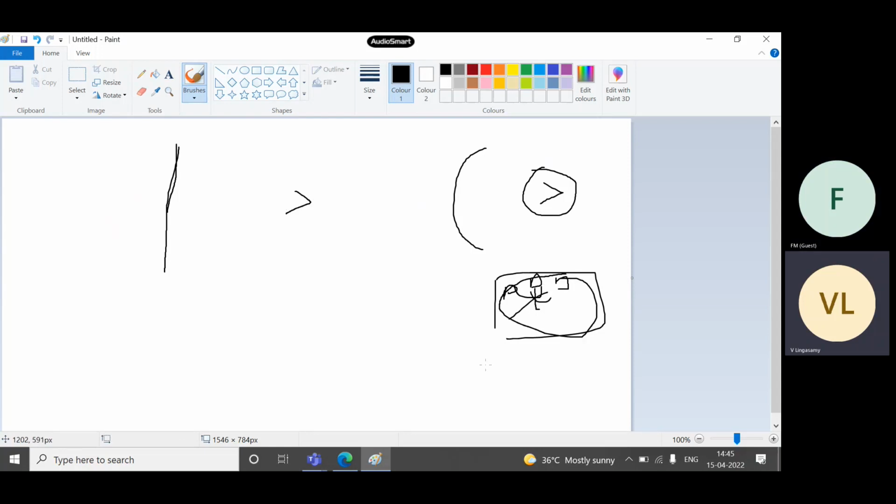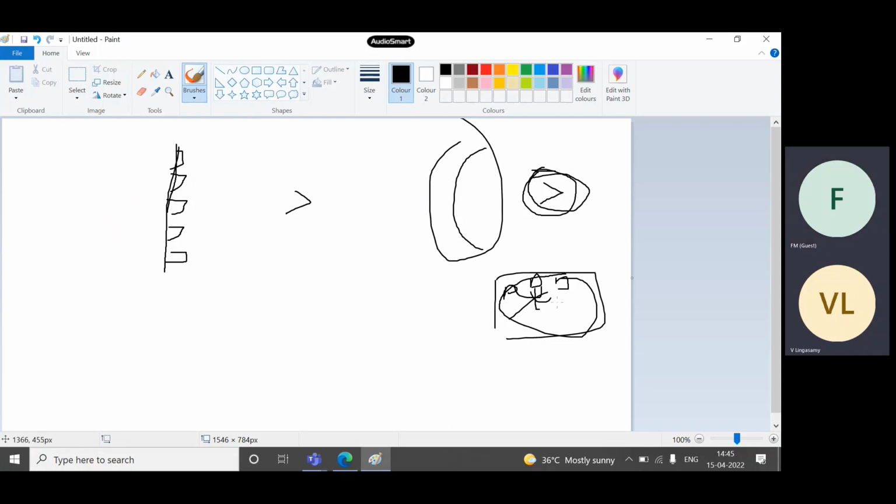For example, we arrange the array elements something like this. So from the parabolic reflector we take only the spatial feed mechanism, and from the array we take only the array of elements, not the feed network. That is what is called a reflect array.